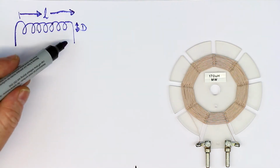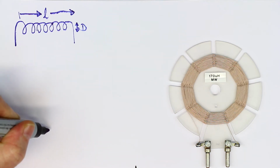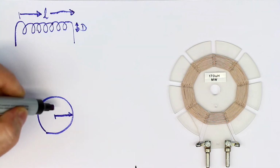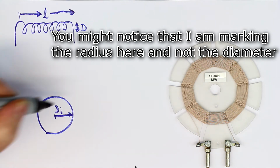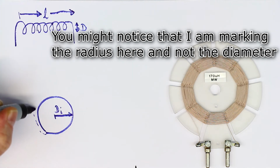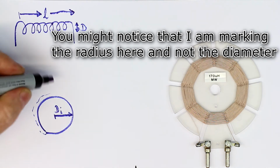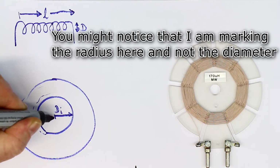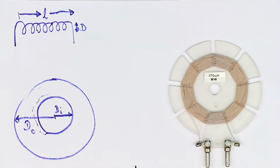We don't have a solenoid winding, but we have a spiral winding with, first of all, an inner diameter where the winding starts. So let's call this di. And then the winding goes spirally outward, so the diameter enlarges progressively and finally reaches an outer diameter, let's call it DO for outer.